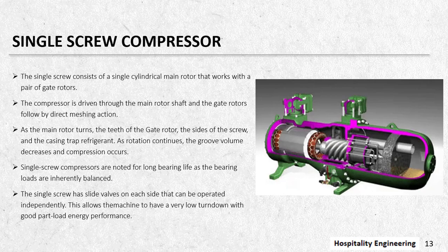Single screw compressors are noted for long bearing life as the bearing loads are inherently balanced. The single screw has slide valves on each side that can be operated independently. This allows the machines to have a very low turndown with good part load energy performance.